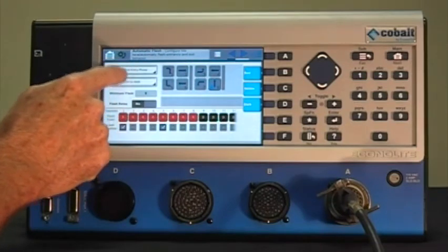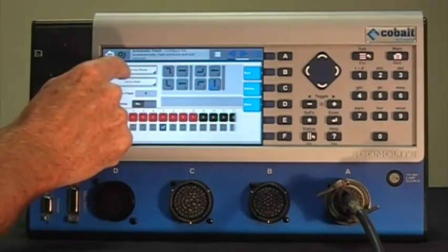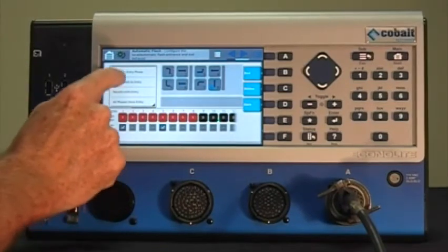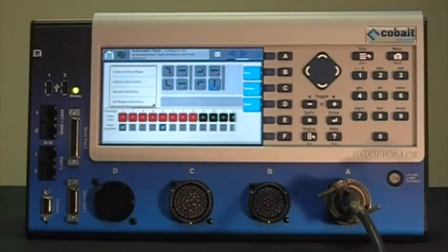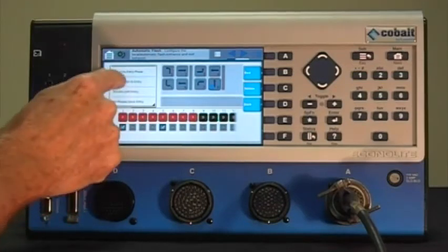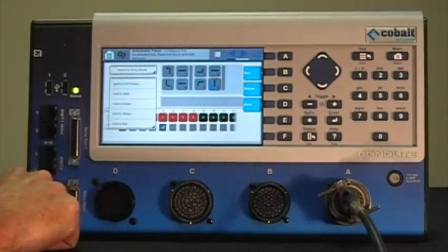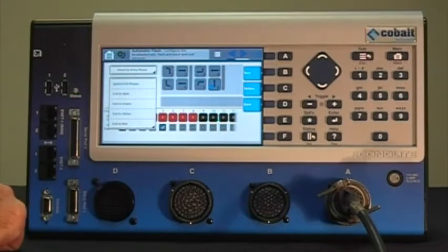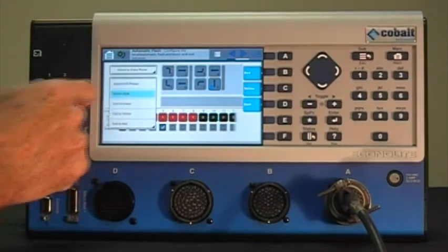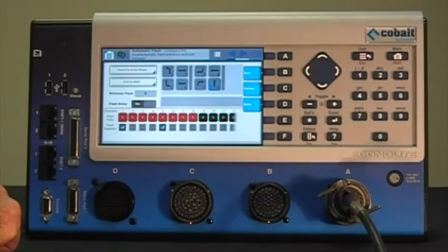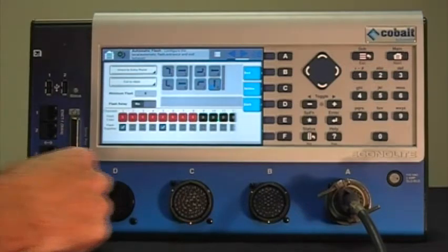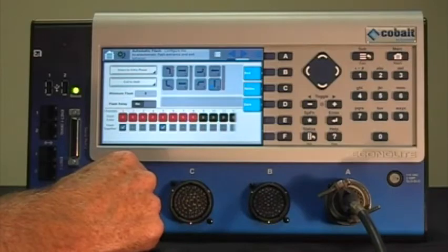We also have the screens to tell it how it's going to go into flash, whether it's going to directly go into flash from phase 8. Is it going to service all active calls, or put recalls until entry, or put all phases on recall and then go into flash. Same thing with exit. You can exit to walk, to green, to yellow, and so forth. So in this case, we'll just leave it to exit to walk from flash. Okay, let's go to the next screen.